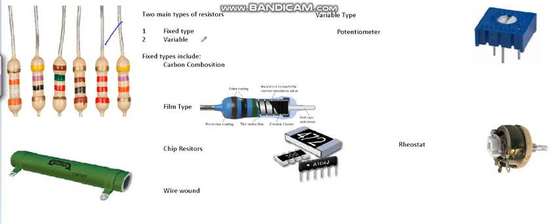So the fixed type resistors, the most common type of fixed type resistor is called the carbon composition. That's what you're seeing here. These are the carbon composition. And the carbon composition type are made from a paste that consists of carbon, obviously, and a filler material. Some of them use like a cermet mixture, which is a fine glass particle. And what they do is they take this paste material and it's mixed up in a slurry. And what they do is they form it onto a non-conductive material, and then they put these conductive rods on there as well, one on either side.